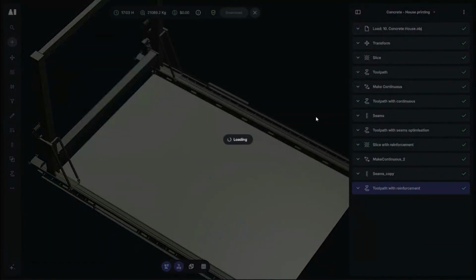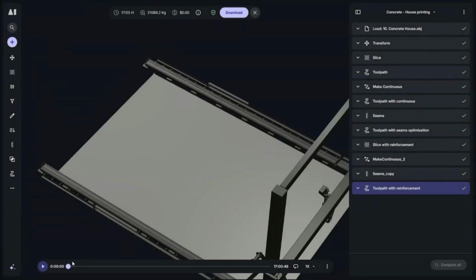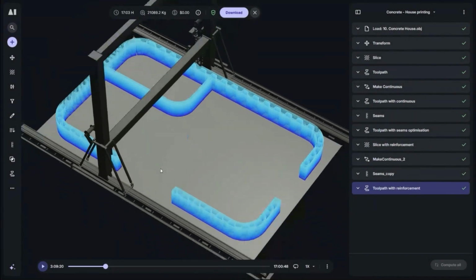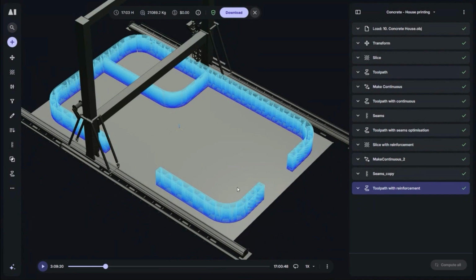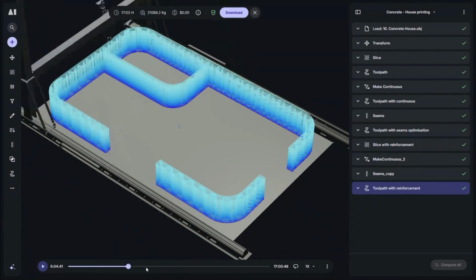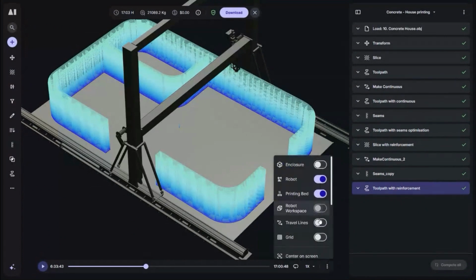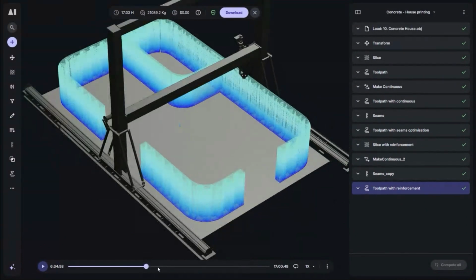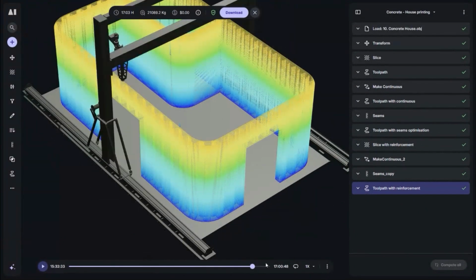And because we can change the position of our seams and we can automate them based on proximity and all these kinds of things, we can minimize jumping time. If you're printing houses like this, you've got different rooms and wall sections, for example, here, until they connect later on. This is an independent section. So you need to make sure that your seams and jump areas are in optimized locations. Mm-hmm.